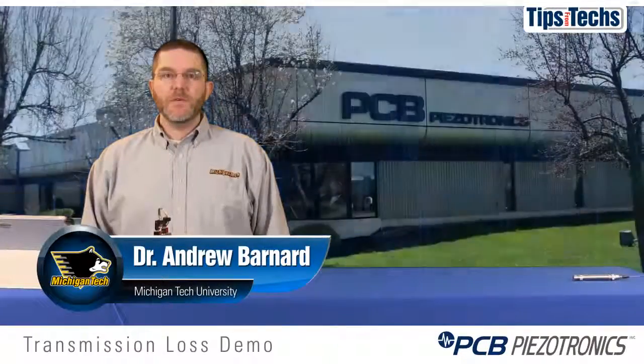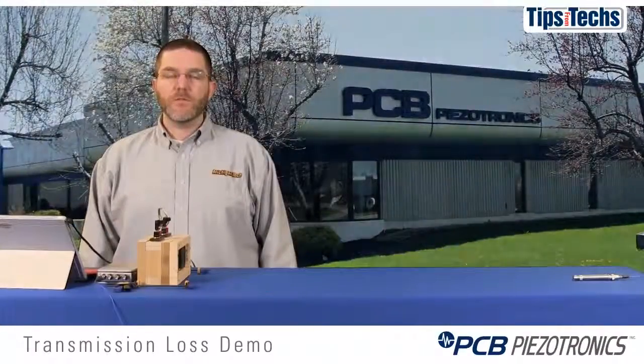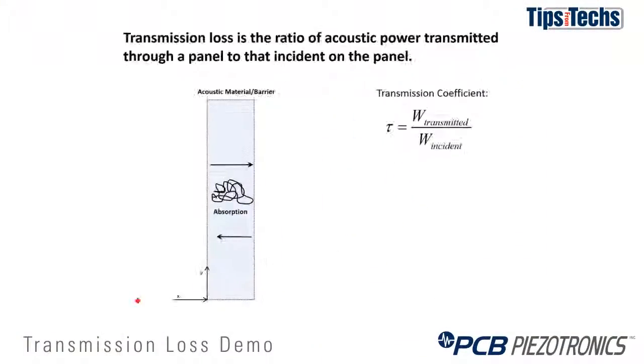I'm here today at PCB Piezotronics to give you a demonstration on the concept of transmission loss. We'll start with a little bit of theory. The transmission coefficient for a material is defined as the amount of sound power transmitted through that material divided by the amount of sound power incident on the material. And here you can see an example of that.